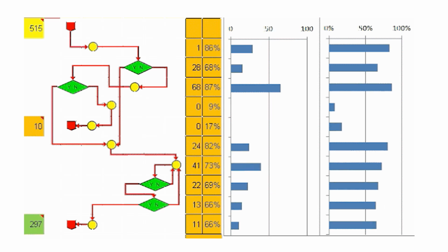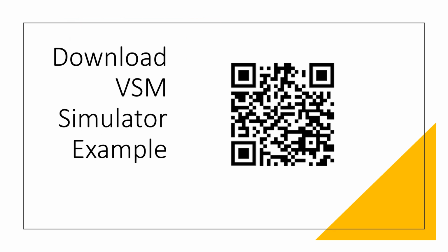Mapping the current value stream is a good starting point to understand how it behaves, but this instant picture may not be representative of its behavior in the long run. To further analyze the value stream behavior, we need variation data on its critical parameters such as inter-arrival times, process times, first pass yields. Download this Excel Simulator, VSM Simulation1.xlsm, from OneDrive.